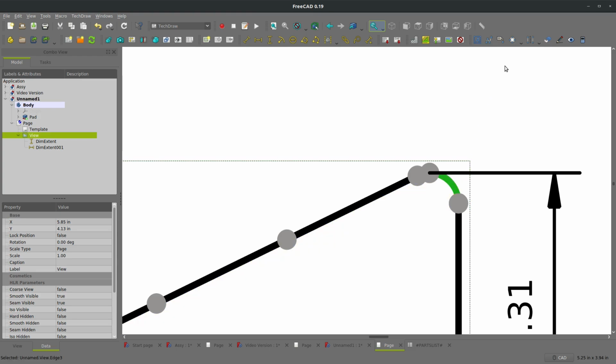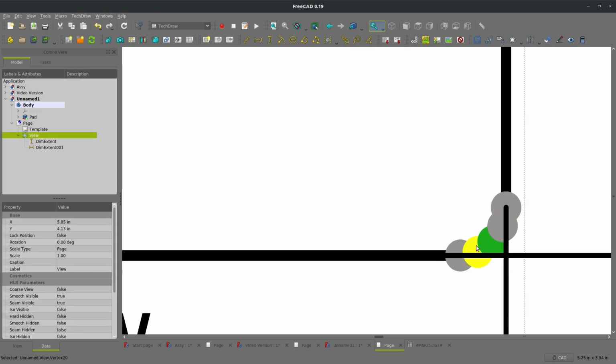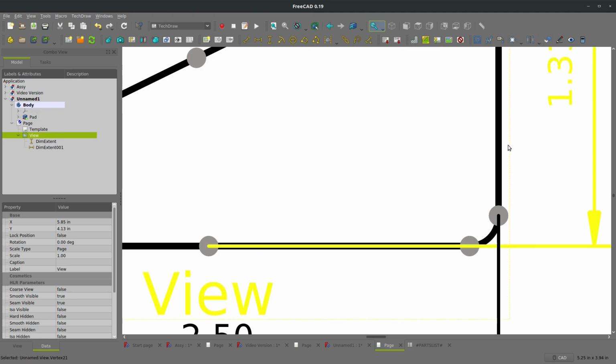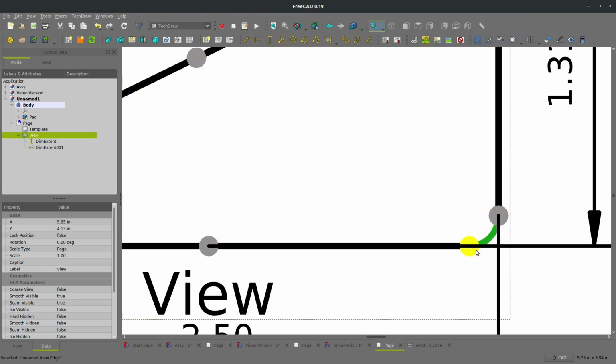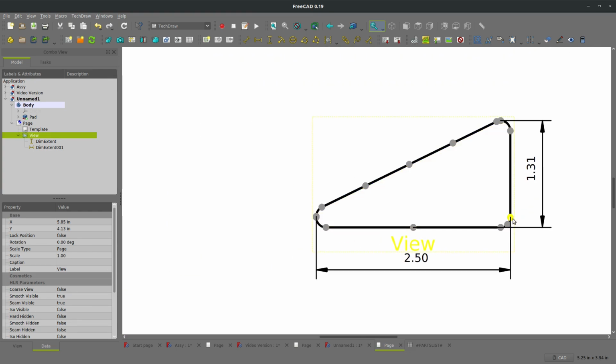Now what if I need to reference an arc center point? Maybe I'll do this arc, or just as another reminder, I can select all of these points, just hold Control and remove them. If I need to highlight the arc center point for some reason, the center point command works on the arc as well, and we can add an endpoint or midpoint vertice.